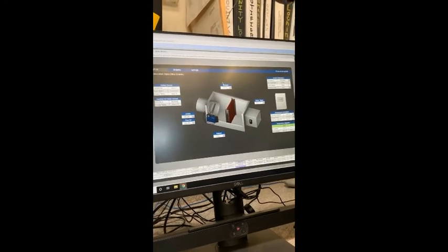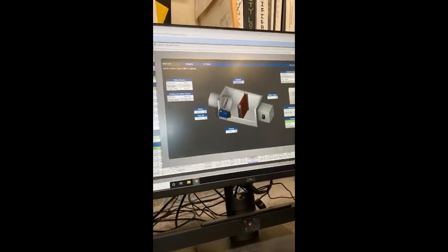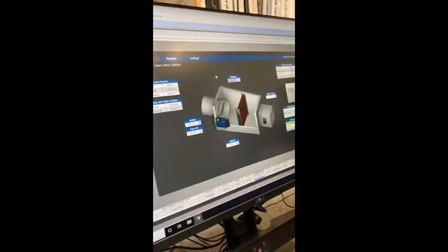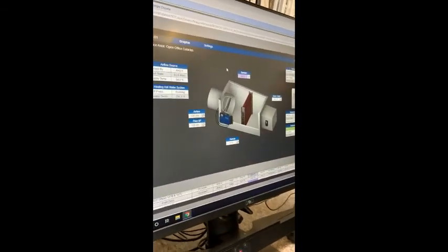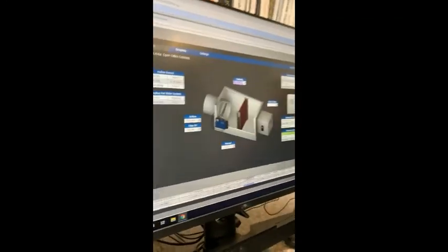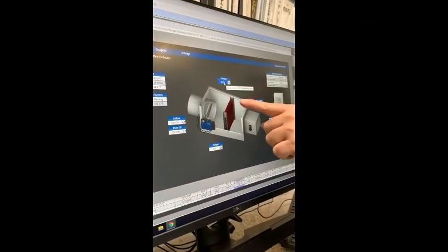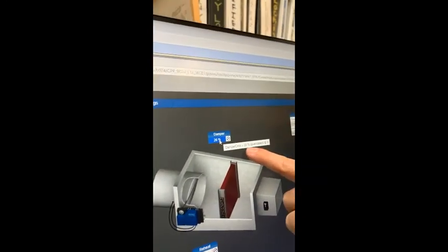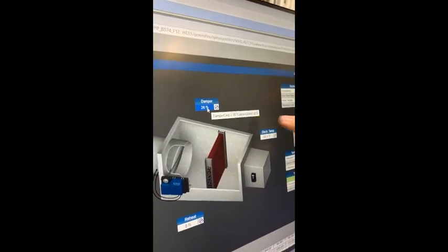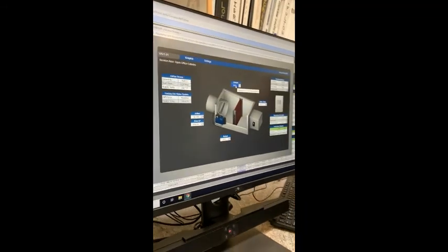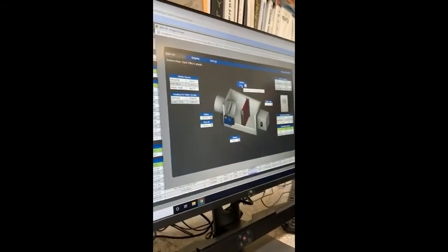and it may take a second for it to show, because basically it is sending a command from here to the JACE, down to the controller, and then the JACE needs to read that point. But we can see here that it's saying that its damper command is actually at 30%, and it's overridden at 8, which means it's the priority that the override writes at.